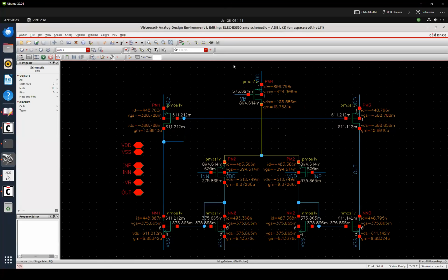So what I'd like to explain in the other way around is, if you remember the current equation of the transistor, although those transistors look like they may go into the subthreshold region, let's assume that all the transistors are in strong inversion and saturation. Then it goes to half mu Cox W over L (VGS minus Vth) squared.